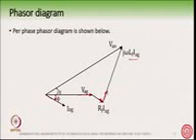So j omega LF IAG will take me 90 degrees, and then I will know the required value of VAN, which is to be produced by the converter. In this particular phasor diagram, the converter has to produce a voltage which is leading the grid voltage, and its magnitude is more than the magnitude of the grid voltage.